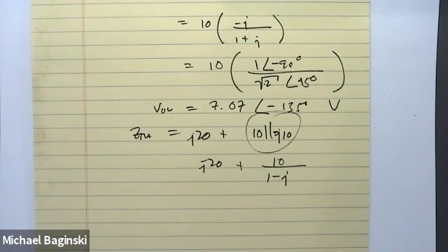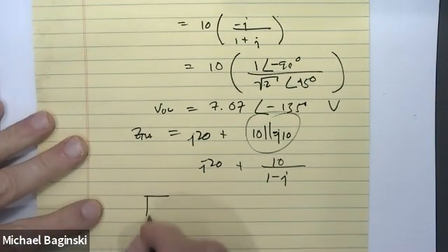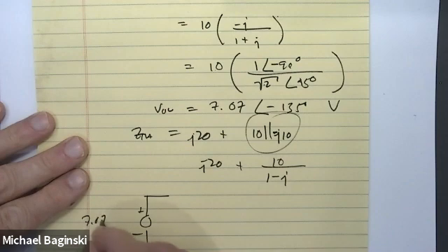Circuit, right? Going to assemble it. All right, so my assembly starts with the open circuit voltage. That's this, 7.07, or really 10 over the square root of 2 if you want. And it's going to be that at an angle of minus 135, right? At minus 135 degrees.